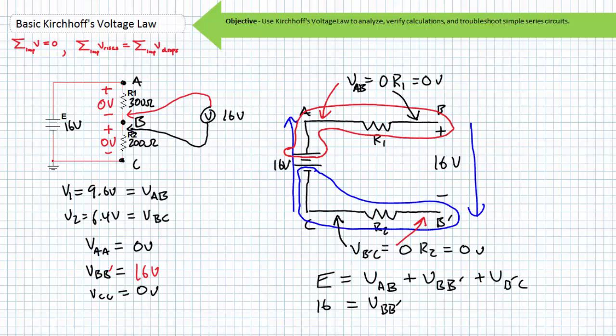This is a little hard for beginning electronic students to understand, but an element touching a voltage source's terminal will assume that terminal's potential at all points within it if there is no path to the other terminal. The only thing preventing a voltage drop is current flow. When current equals 0, IR drops, or voltage drops, equal 0. The only thing preventing current flow is the open circuit, and therefore the voltage drop will occur across the open circuit. KVL explicitly states this, as does playing loosely with a couple useful series circuit properties.